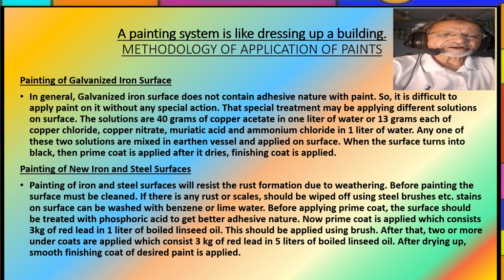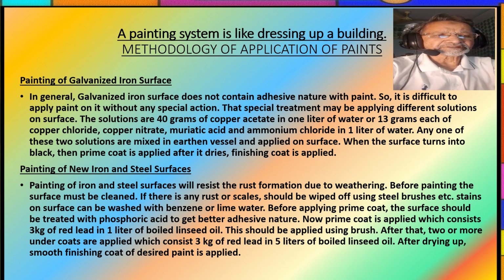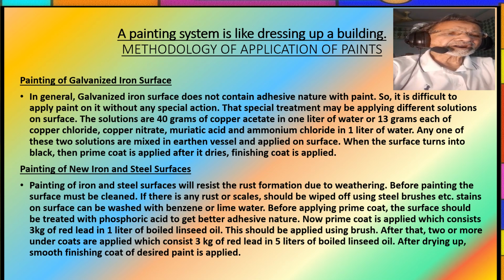Painting is to be done now. Use acrylic, latex paint, epoxy or polyurethane based paints which are known to adhere well to primed galvanized surfaces. Apply thin coats only, because it allows the coat to dry completely before applying the next coat. It takes several hours, maybe 5 hours or something like that. Curing: do the curing of the surface so that all the dust and everything is removed.